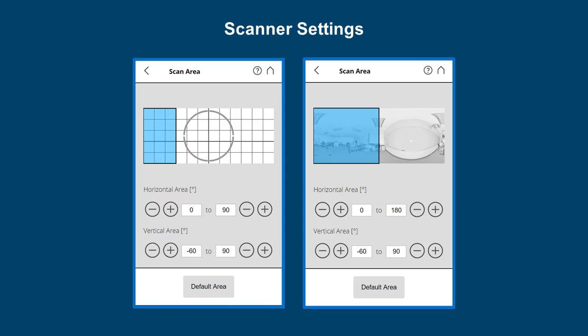Thank you for pointing that out, and I forgot to add that to my slide presentation. But if you're looking at the LED screen of your scanner, the zero location of that scanner is to your left. So I'm going to do the visual. If you put your arms straight out and you look to the left, if you're looking at the scanner directly in front of you, left is 0, right is 180, and then 90. If you take that right hand and you put it right in front of you, that's 90 degrees. So you have to make sure that the scanner's capturing the area that you told it to. So we're moving around a 360-degree compass clockwise.